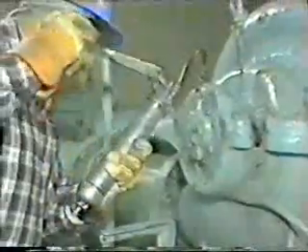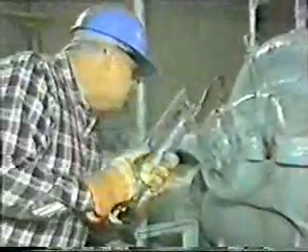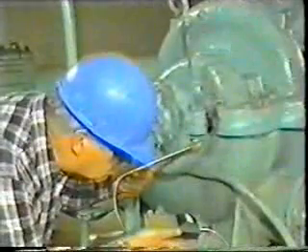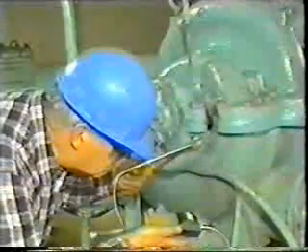To verify that there is too little grease, you can add grease in accordance with your facility procedures. Then, monitor the temperature to see if the temperature comes down. A temperature decrease would indicate that there probably had been too little grease on the bearing. So in this case, verifying the cause of the problem and fixing both the problem and the cause are the same thing.